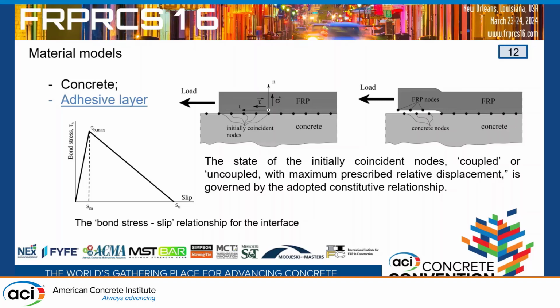Sure. Thank you. There is one question here. Thanks for sharing. My question is about the cohesive behavior, because for this type of test, the main problem is the contact. For the layer, are you using a zero thickness cohesive element? No, I do not use cohesive elements. I have initially coincident nodes, and I just govern the position of nodes.